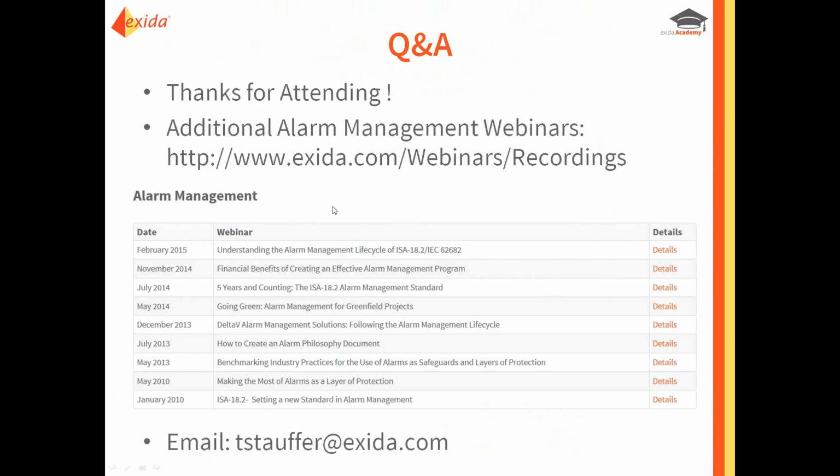One other way you would judge might be based on where those alarms come from. If it's an IPL alarm in your BPCS, chances are it's not that important that it should be a safety alarm. If it's a safety alarm, that alarm probably either needs to be part of your SIS, or at least be in a dedicated system that uses high reliability hardware similar to what an SIS would.